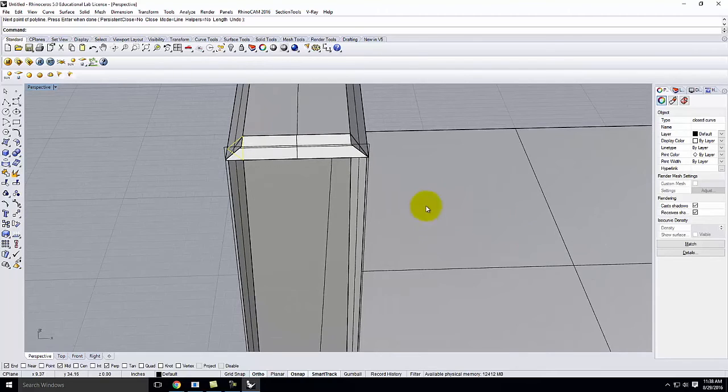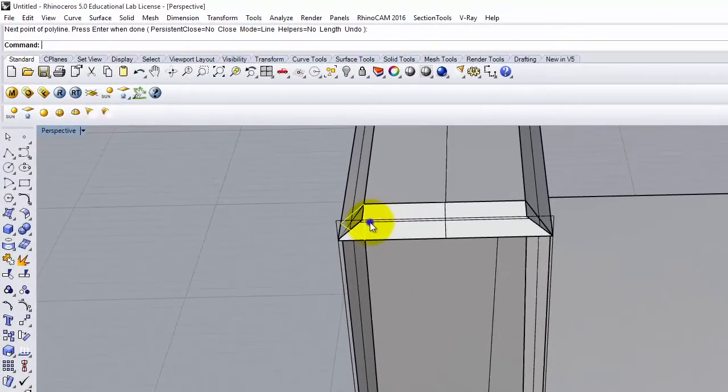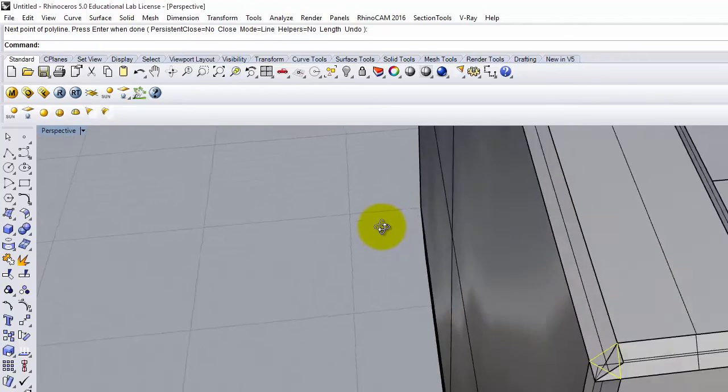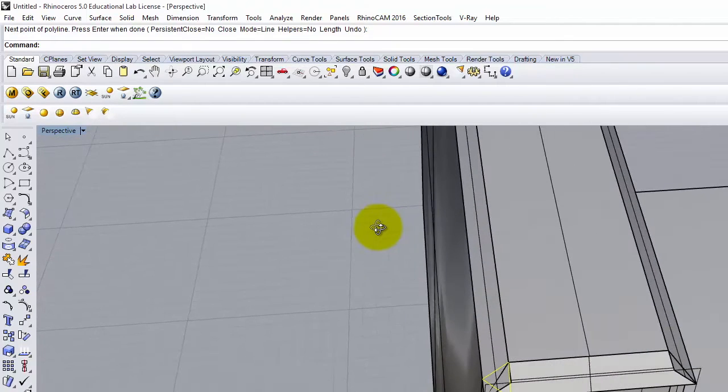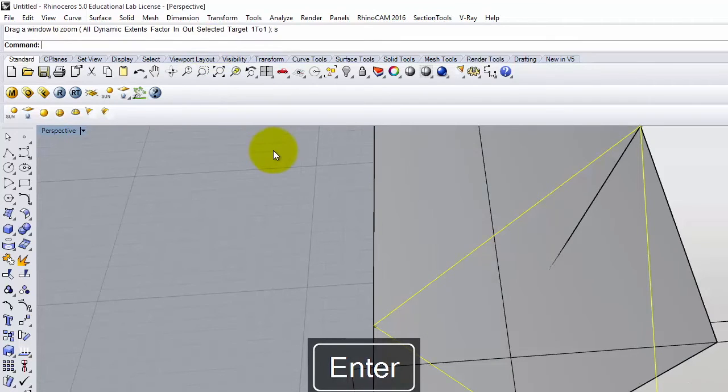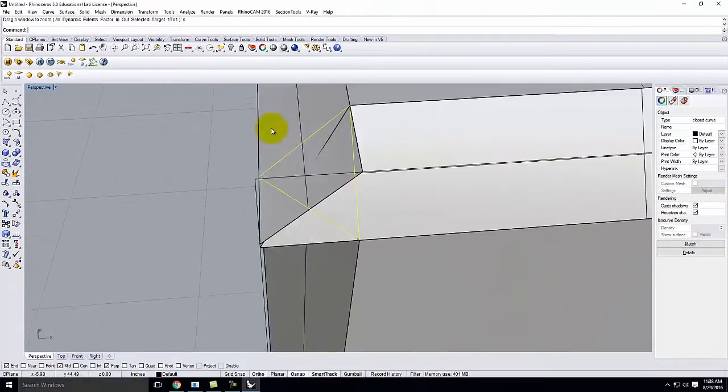You probably also will notice that as you're working with this, zooming or rotating or orbiting can be very, very challenging. See how when I try to orbit and I barely move the mouse, it's jumping off the frame? If I select this little triangle after I've drawn it, I type Z for zoom and then S for selected, or choose selected here, it will reorient my entire view around this one object.